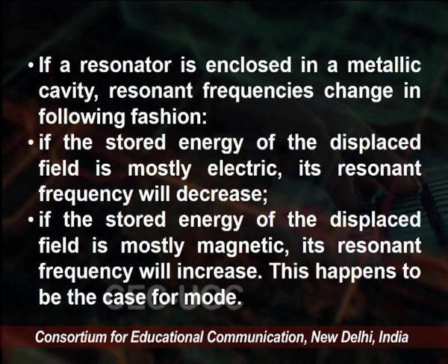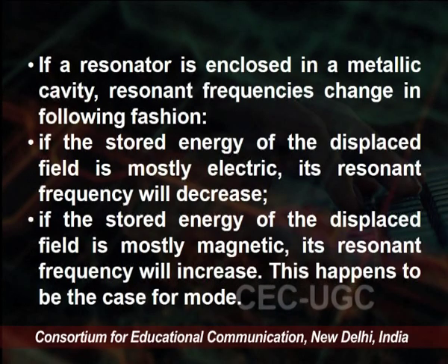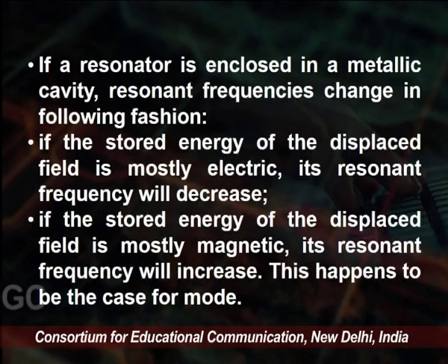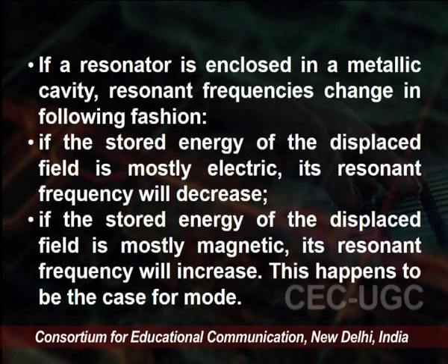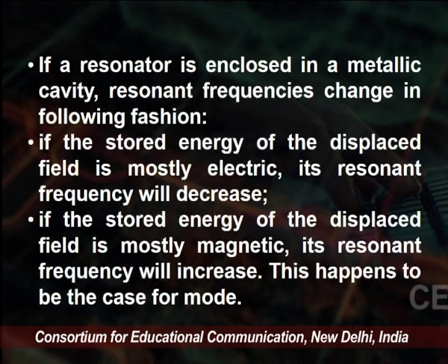Number 1, if the stored energy of the displaced field is mostly electrical, its resonant frequency will decrease. If it is mostly magnetic, then its frequency will increase. This happens to be the case for this mode.